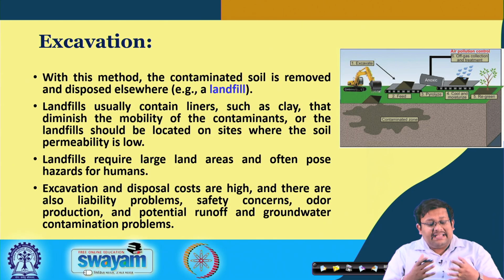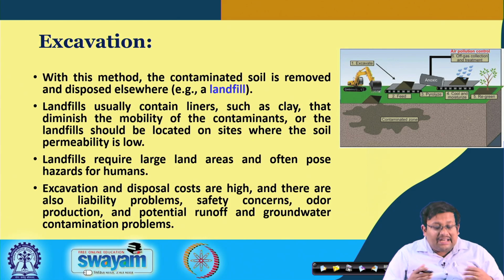A landfill usually contains liners such as clay that diminishes the mobility of the contaminants. We have already talked about the organoclays. So, when we put the lining with the help of clay, it contains those contaminants within that area, or the landfill sometimes should be located on sites where the soil permeability is low.